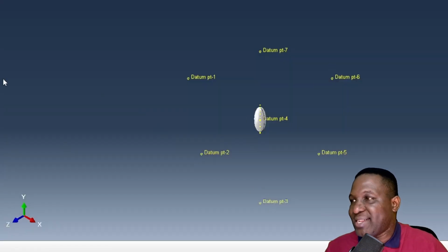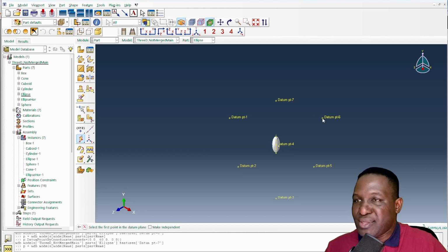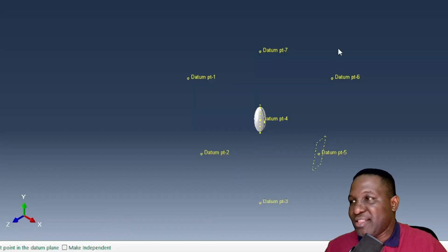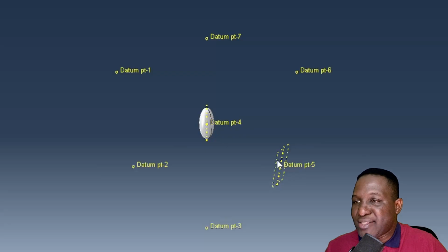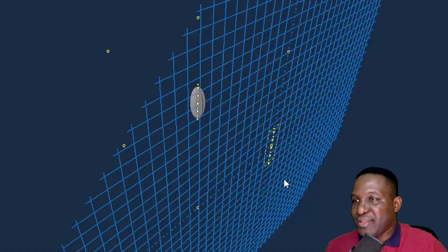So I'm going to use the YZ plane, and we're going to do this by clicking on that. So that creates the YZ plane. And then I need the vertical axis, which I click on. I select those 2. That gives me the vertical axis. And then I can extrude-cut based on that plane and based on the vertical axis.